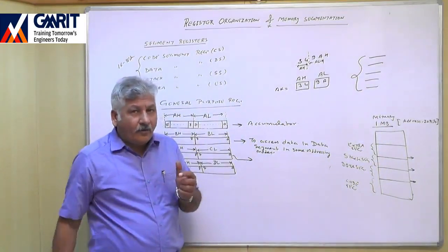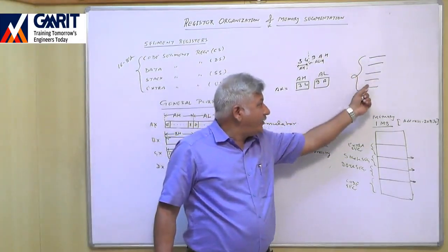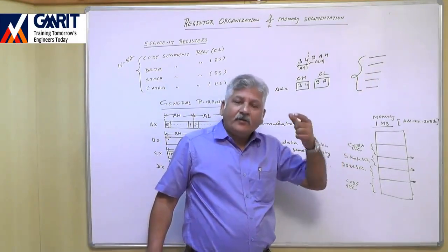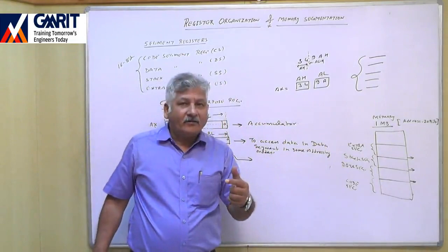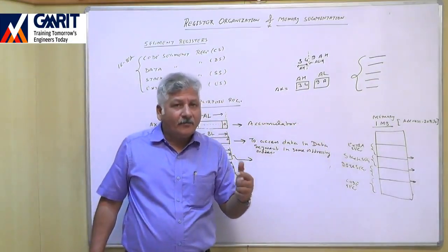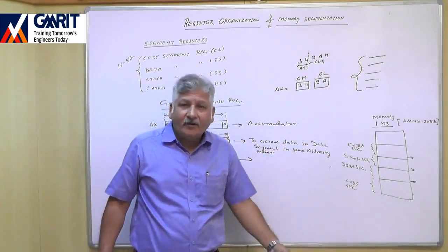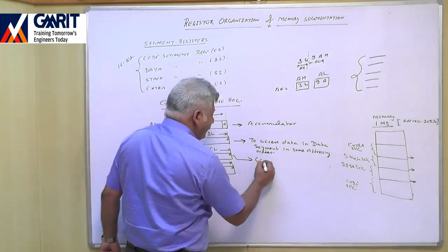To identify whether we have completely executed this loop n number of times, the CX register is used as a counter to check whether we have completely executed these instructions n number of times or not. So this CX is used as a counter.